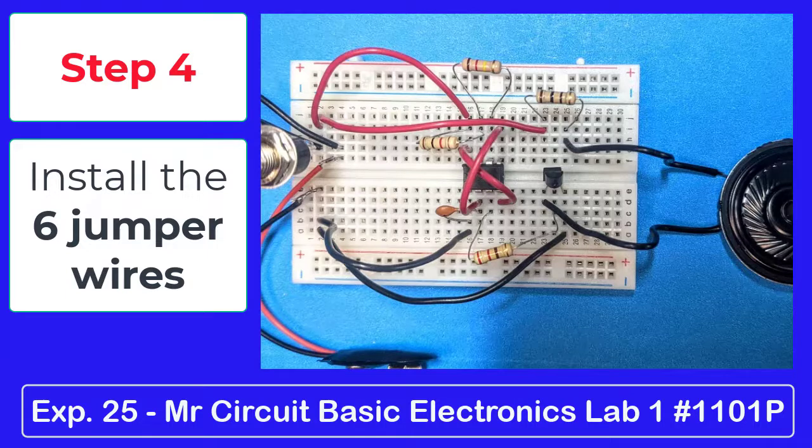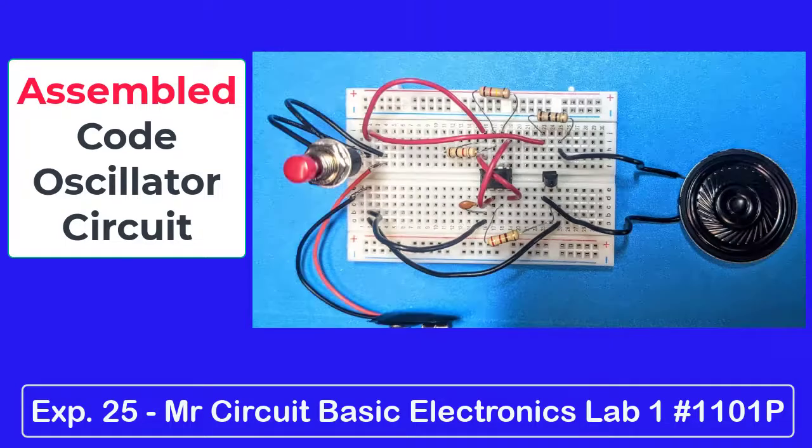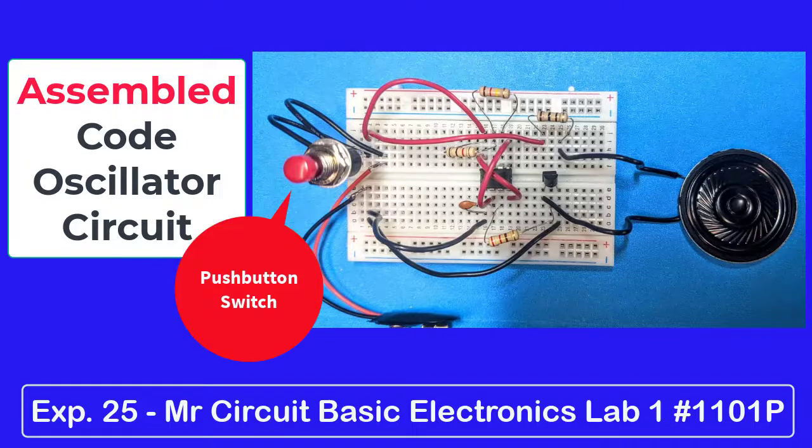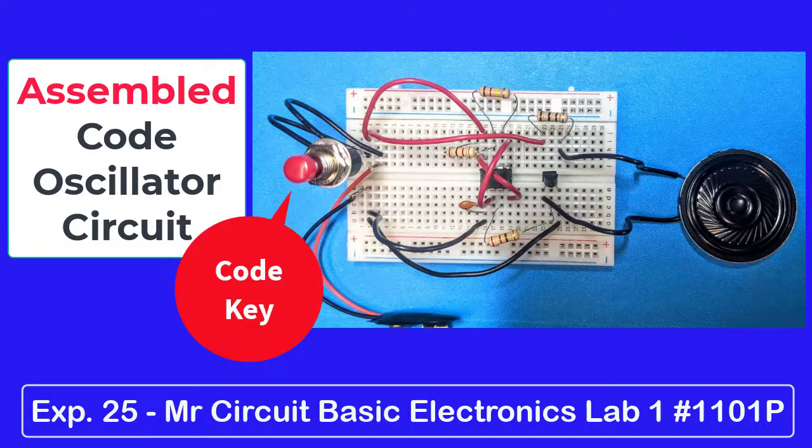Check your wiring one more time, comparing it to the pictorial diagram. When you are sure that you have put it together right, touch the battery to the snap. Nothing should happen until you press the push-button switch to cause a tone to be emitted from the speaker. By using the push-button switch as a code key, you can send a code of audio tones.